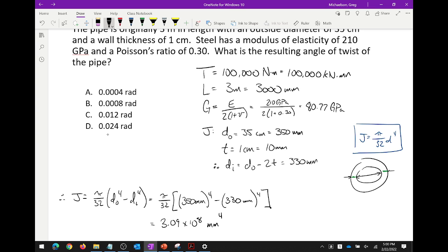And so if you compute L over R, you get a unitless quantity. And L over R, as we know, has very important applications in the world of mechanics. It is an expression of slenderness. In steel design, we have limits on tension member slenderness, and in compression members, the larger the slenderness, the lower the buckling capacity. Remember that? So that's coming later in steel design, and we may talk about that on Thursday should we have time.